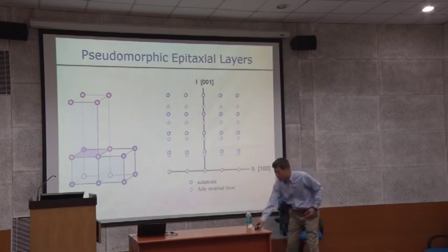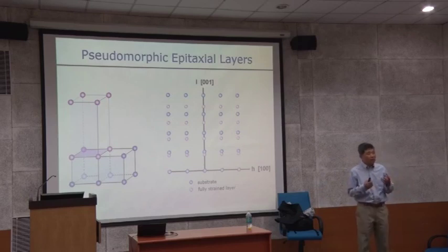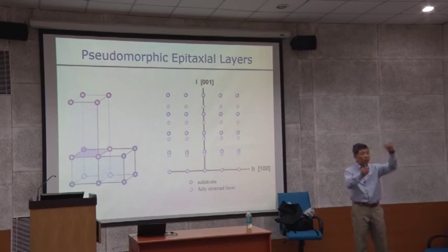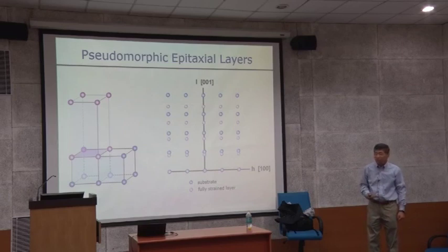this one is exactly the same example of a barium titanate thin film grown on strontium titanate. When you grow barium titanate, that is big. So when you grow it compressively, you compress the strain and elongate it. Remember this? When you do that, this is what the actual reciprocal space looks like. What they mean is you have this lattice, the blue one, the unit cell of strontium titanate, and the unit cell of barium titanate.